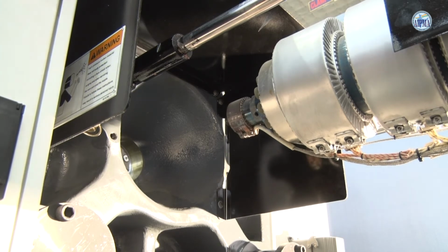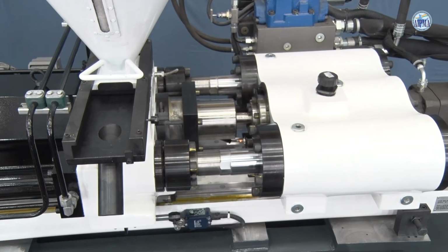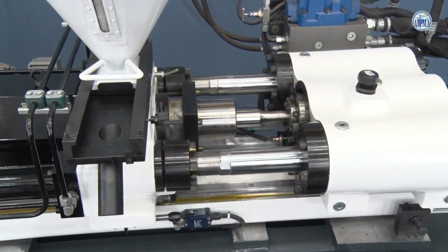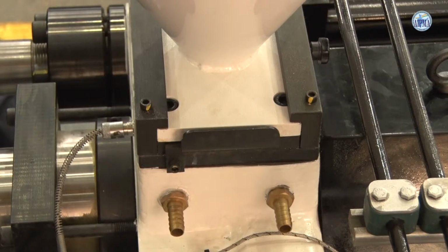Purge the barrel with recommended purging material. When it is visible, the melt coming out of the nozzle is finished. Stop the screw rotation and retract the screw, minimum equivalent to screw diameter, to release the screw tip from the melt envelope. The feed throat cooling should remain on. If the shutdown is only for a short period, now the machine can be totally shut down.